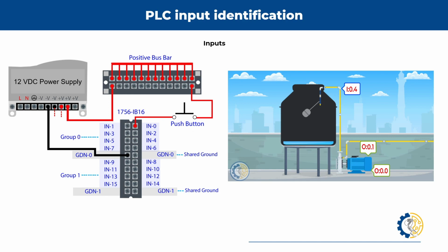This is an electric diagram, but we need to connect a jumper for whatever input that we need to our other end of our push button, which is normally open. And on the other side, we're going to connect directly to our voltage, our positive voltage.